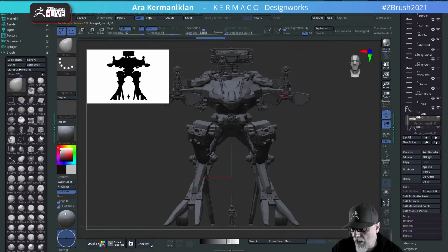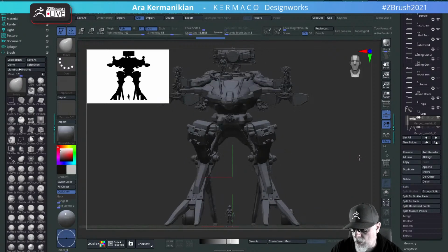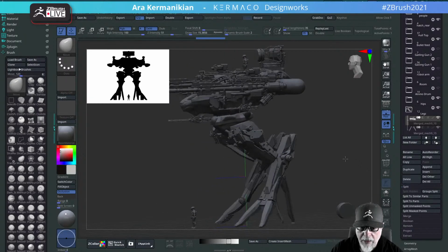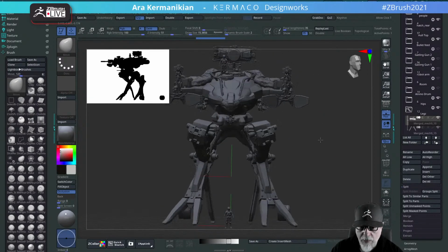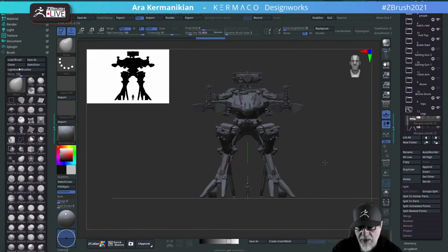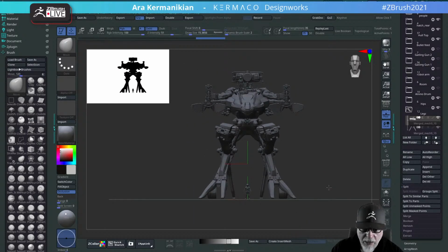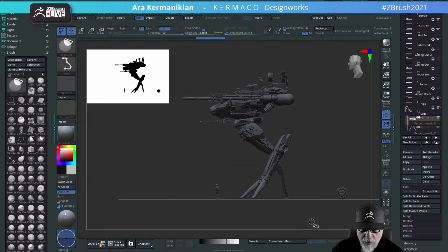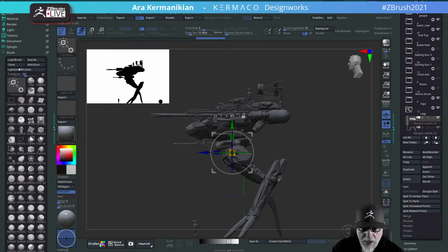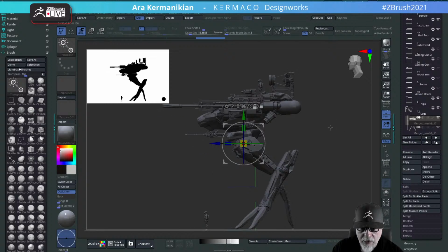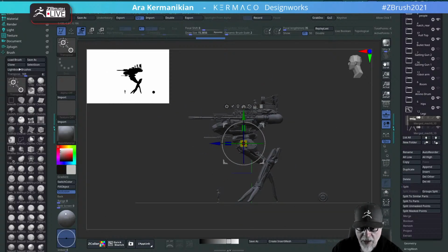Okay. All right. Do I use dynamic subdiv with crease all the time? I use it all the time. Do I keep the subtools disconnected? Of course. There's no sense in having all this be connected for any reason. The good thing is that if it's disconnected, you can do things like, if I want to rotate that top part, see how it rotates, I can always go to things like transpose, turn everything on. So now basically I'm transposing everything.